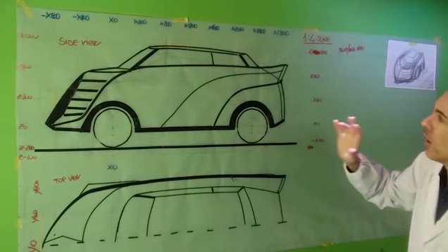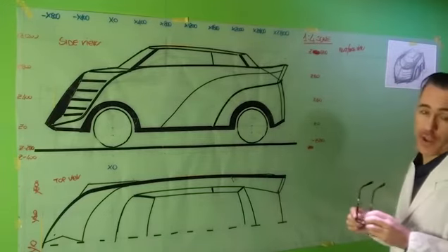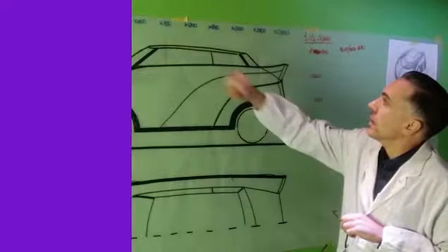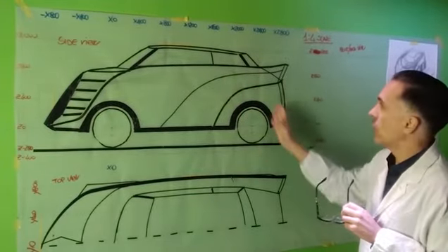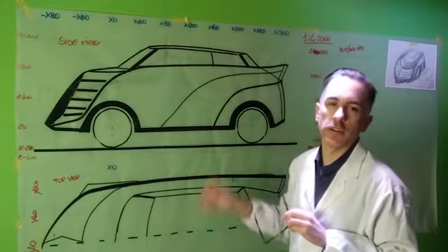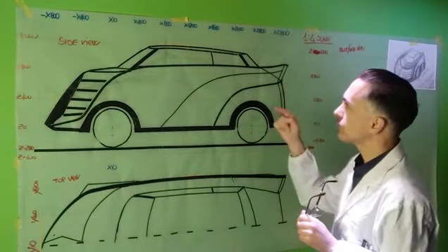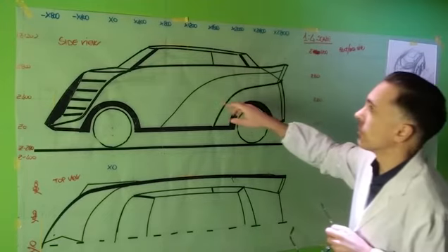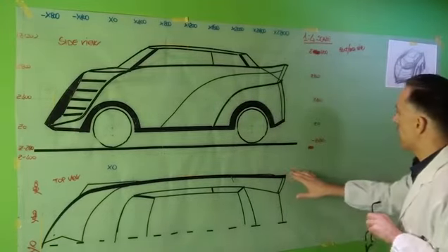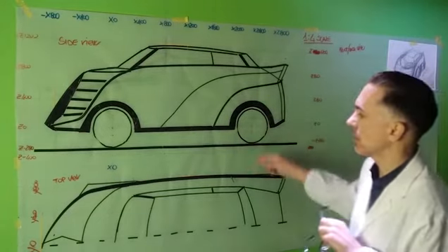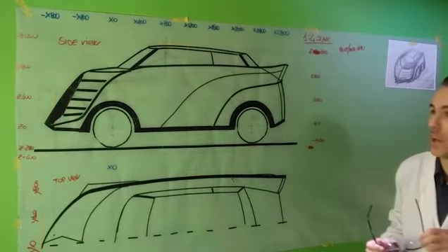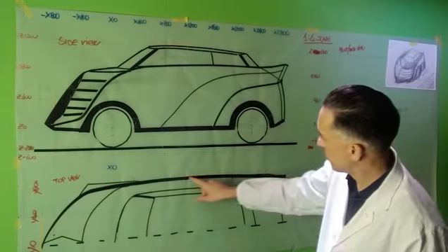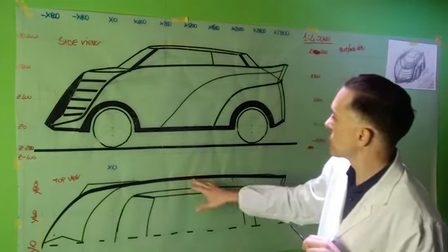I just want to remind you what a section is and therefore also the usefulness of the grid. Because depending on where I have to do the section, with a grid I have the exact reference. So in this case, on the x1 to 1000. And the section is a net cut of the object throughout its volume. So this was and still is the usefulness of the grid lines, that give us the exit point where I want a section. But remember that in the development of a model and of the main volumes, the maximum section must always be used.